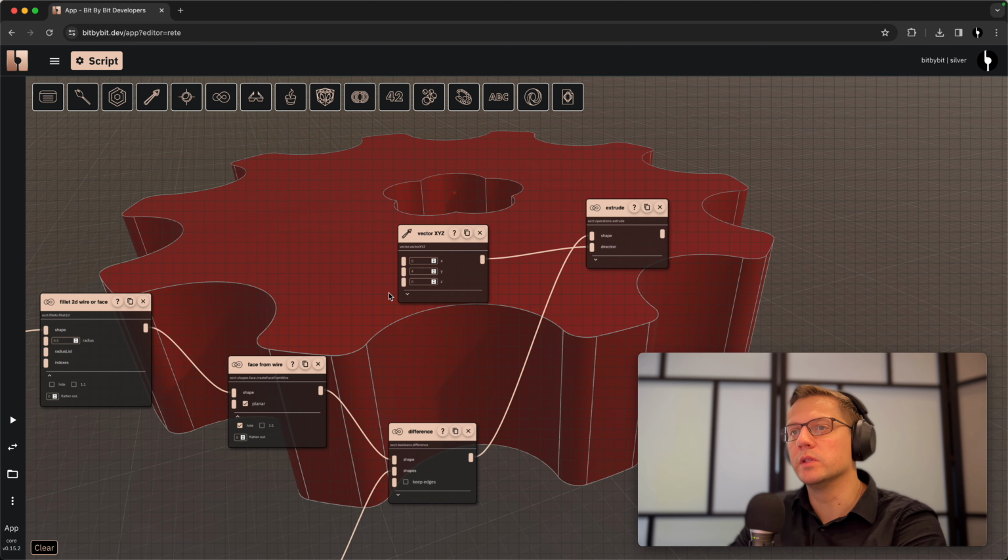And for that we will use a nice list command called pattern. You can always just click the right button and click pattern. So you see here get by pattern. Patterns are nice because you can just define the pattern how you want to filter out the items, and it's a Boolean list. You can hover here on this pattern input and you see here a highlighted type, Boolean array.